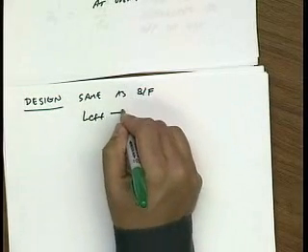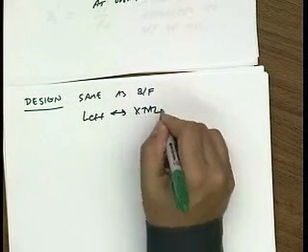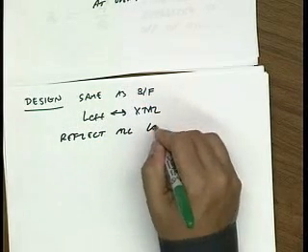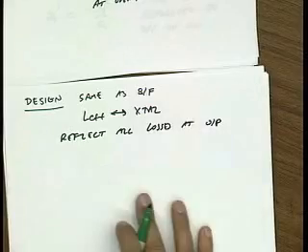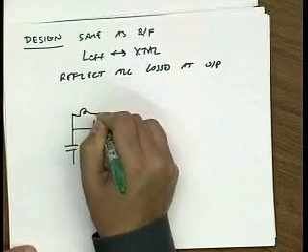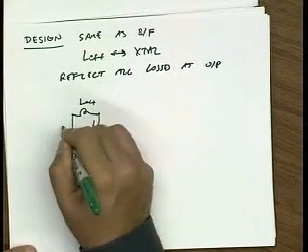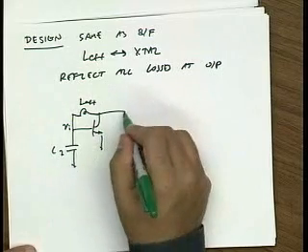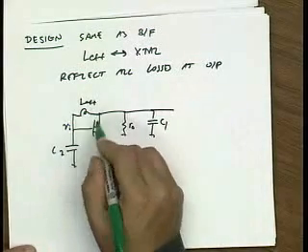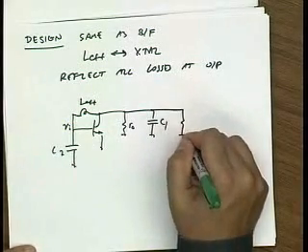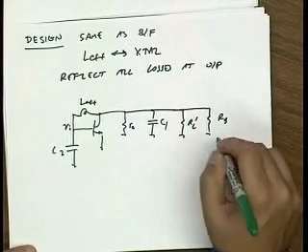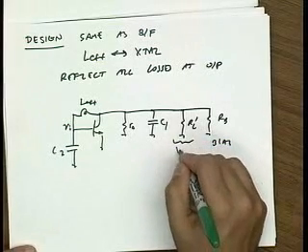All we have to do is replace the crystal with an L effective. We reflect all the losses at the output, and so our equivalent circuit looks like some L effective here. This is V_n, this is C_2. Let's say this is the R_O of the transistor. This is C_1. I took the loss here and reflected it to the output. That gives me R_L prime. Might have a bias resistor, say R_B. This is the crystal losses.